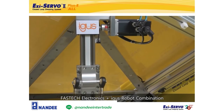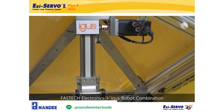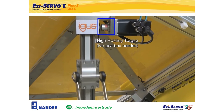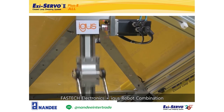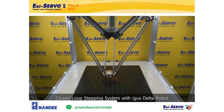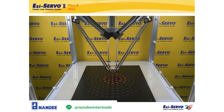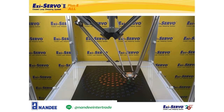The Delta robot of Aegis has a short pitch motion due to its belt pulley structure. It is the characteristic of the stepping motor that generates the maximum force when stopped, so you can control the Delta robot without a gearbox. Thus, you can directly install the robot to the motor shaft. If you look at the actual motion of the motor, it is operated under the short pitch motion to move the Delta robot, due to the Delta robot's mechanical structure. A stepping motor is optimal for such short pitch motion.